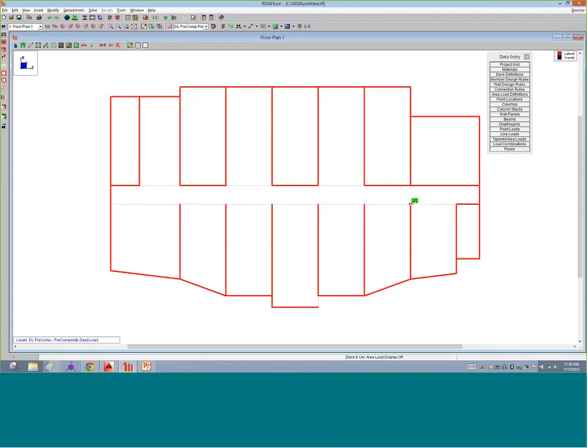Now, I'm just drawing in all of these walls. What these walls represent for me is basically my lateral system. So I'm just outlining what's happening on this lateral system. And what you'll see is that I have some gaps in here. I'm going to put some beams or collector elements in for these gap hallway elements that I have here. So I've laid out all of the walls that I want to put in. Oops, and it looks like I just neglected one little wall here.